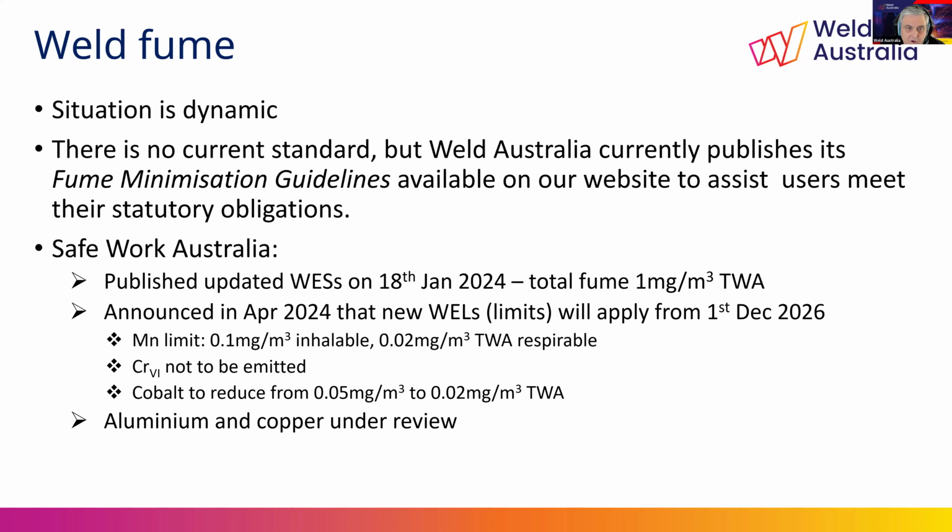And it's also planned to reduce cobalt from 0.05 to 0.02. But there's more, unfortunately. Both aluminium and copper weld fume is currently under review by Safe Work Australia.